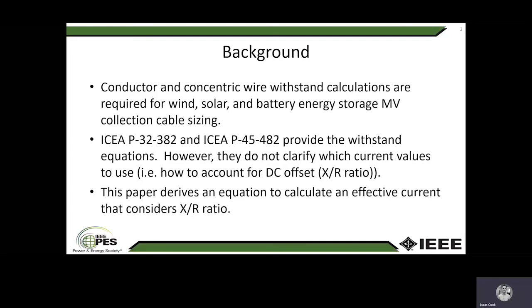What these equations give you is the ability to determine either the amount of time that a conductor can withstand a given fault current, or the fault current that a conductor can withstand for a particular time, and that time being the clearing time of your fault scenario.